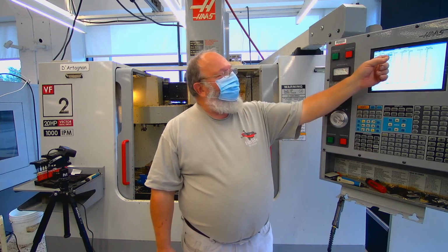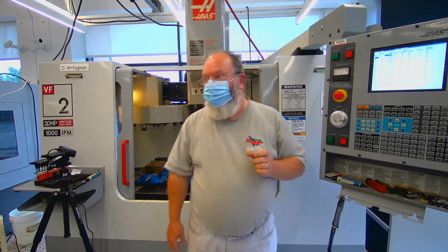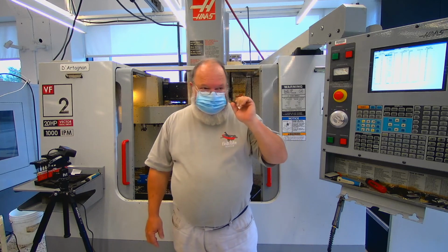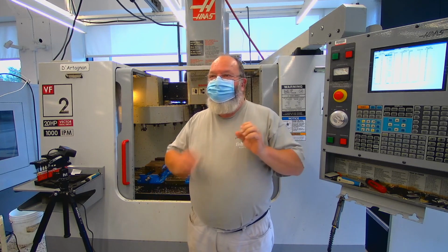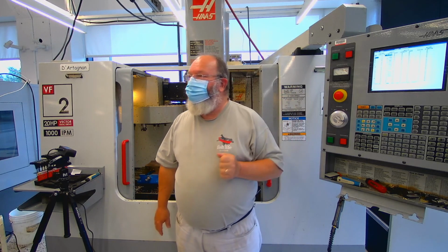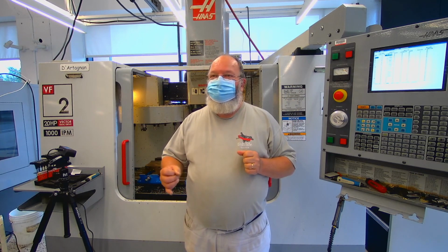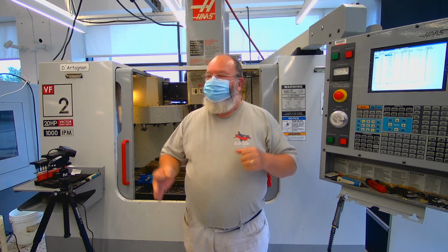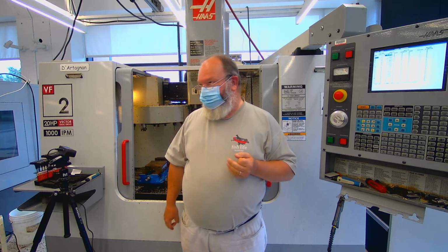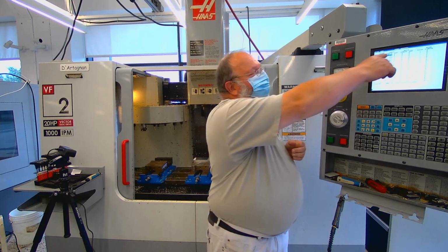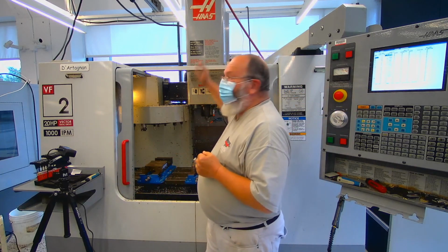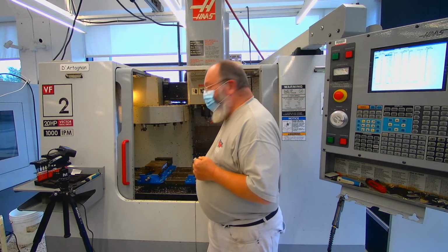Again, the people who wrote this control call it a geometry offset. Just like Klein milling, not a machinist on the face of the earth calls it a geometry offset. Call it a TLO, because that stands for tool length offset. But we're simple and we need to know exactly what it means. Each one of these distances is how far off of Z home to get to here.